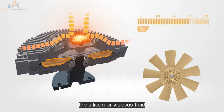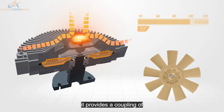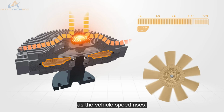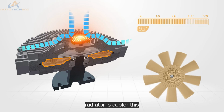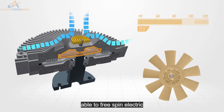The silicon or viscous fluid is able to change its viscosity with heat and is channeled in such a way that it provides a coupling of the fan hub to form a semi-locked drive. As the vehicle speed rises, the airflow through the radiator is cooler. This has the opposite effect on the control valve and viscous fluid, so the hub is able to free spin.